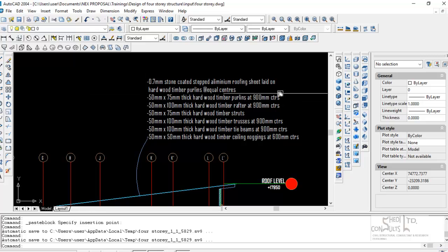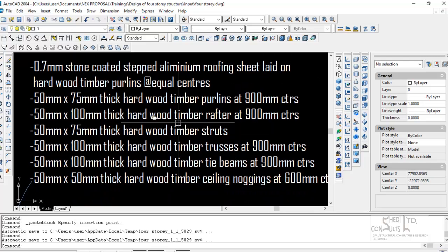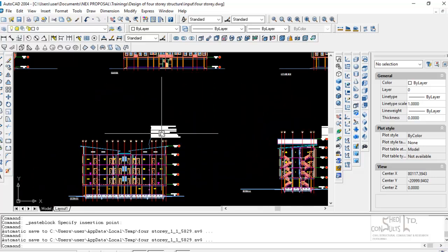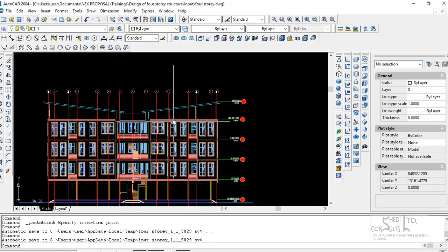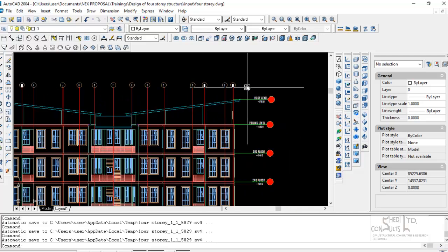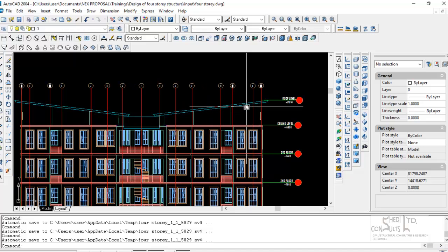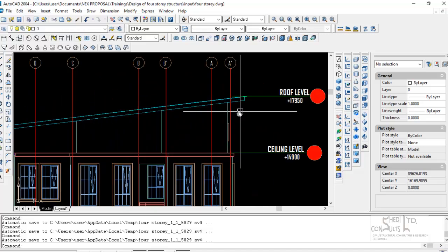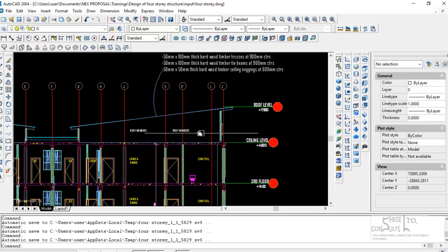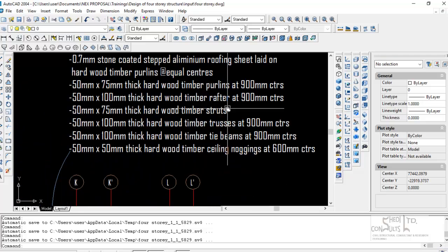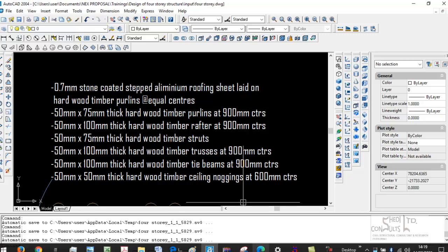Okay, and the roof truss is made up of hardwood. So you have your upper chord, lower chord. So this is a mono-pitched truss arrangement. You can see it slopes in this direction and slopes. So you have a dual mono-pitch truss arrangement, and the truss will comprise the rafter, the pole lines that carry the roofing sheets, and then it will also comprise the struts and tie, okay, which are the roof truss members. All of the loads together from detailed analysis will not exceed 0.3 kilonewton per meter square.